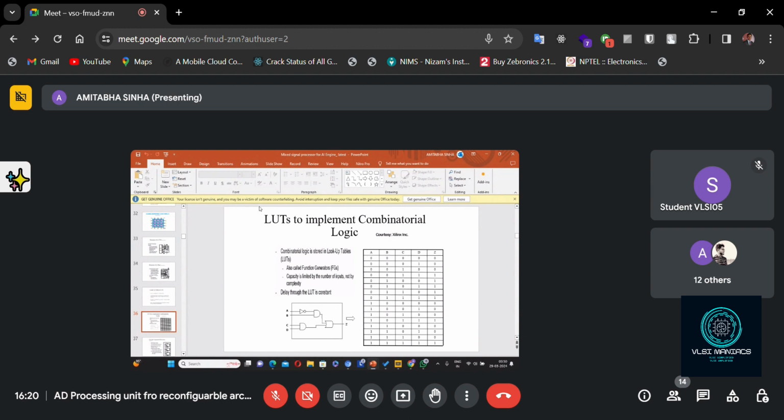But now another type of FPGA has emerged in the market, called dynamically reconfigurable FPGA, or on the fly reconfigurable FPGA. What is the meaning of that? On the fly, in the sense, let's say within an FPGA there are 4 portions A, B, C, D. Let's say A, B are static, and D is getting changed.